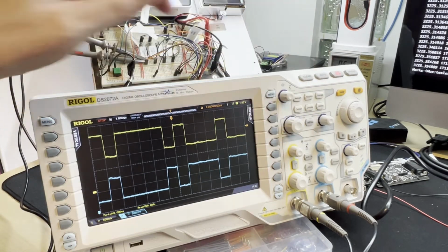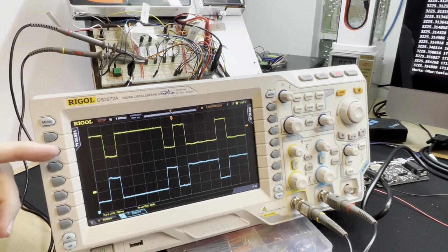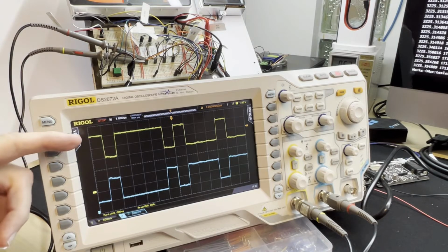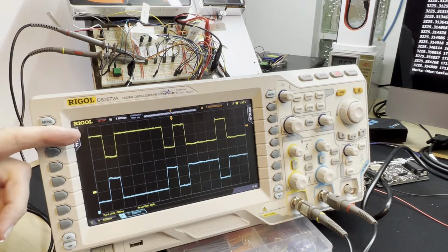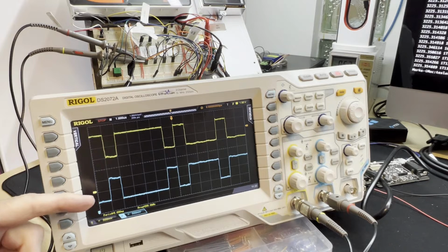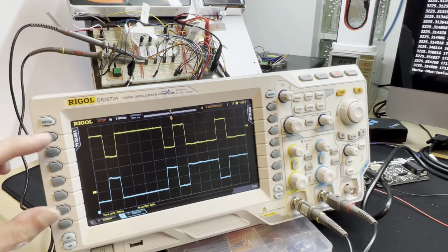We can see the 2 wires are mirrors of the signal. When one is high, the other is low. This is so that any interference, increasing or decreasing the voltage on the wires, will likely affect both equally. Remember that we are only looking at the differential, the difference, so that should be unaffected by such interference.